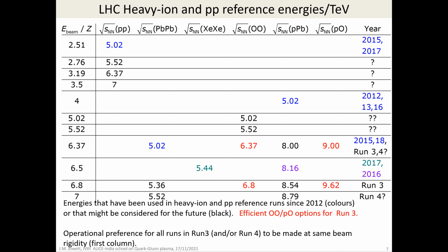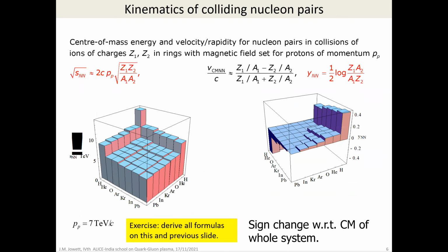The beam pipe, I showed a picture of it somewhere. No, it was in yesterday's lecture. You can see from the color that there are actually two pipes. There's the beam pipe itself, the vacuum pipe. Inside it, there is a second kind of liner called the beam screen, which is another beam pipe inside the other one, which has actually got a lot of holes in it. The outer beam pipe does the cryogenic pumping because it's colder. The inner one is a bit warmer. It's at 20 degrees normally.